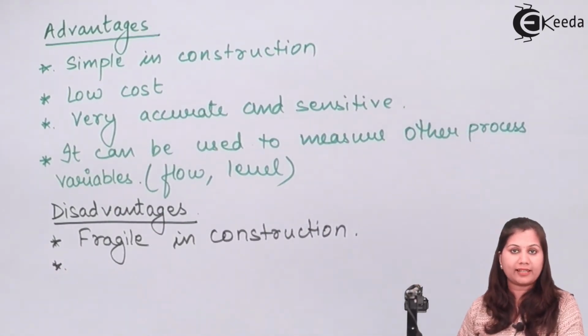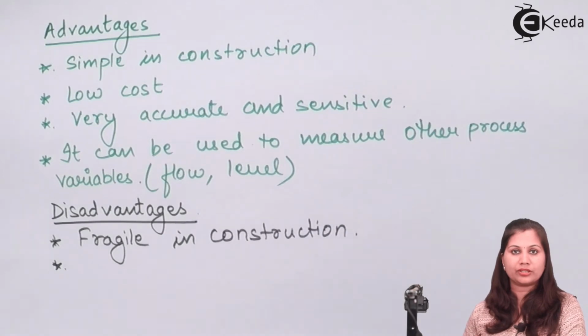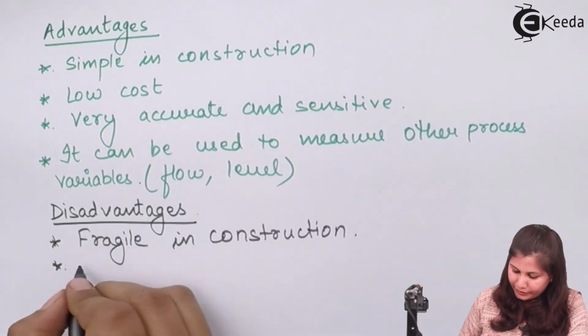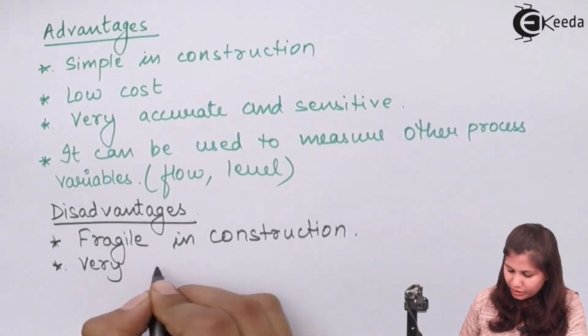Also, it is very sensitive to temperature changes, because if temperature changes, then the density of the fluid is also going to change, and density changes are going to cause variations in the reading. So it is very sensitive to temperature changes.